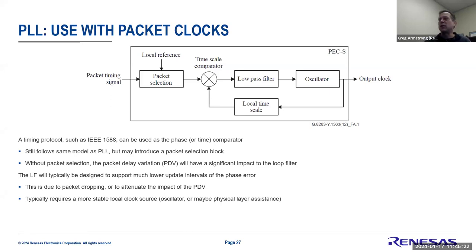And then you steer your local oscillator to represent that clock. And the feedback mechanism there is effectively your local timestamper. And then the protocol runs again and makes that measurement. And again, the idea there is you're trying to get that offset from master to converge to 0, so that you know that your local clock is now synchronized precisely to your grandmaster clock.